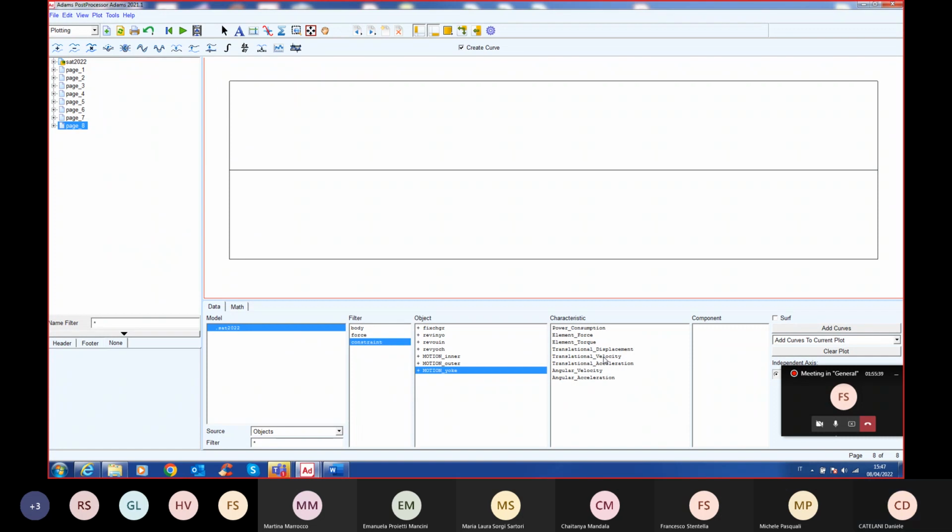For example, we have 3 motions. Every motion is defined with a function of time. And the motion has to actuate a system with inertia. Which is the torque a motor has to apply to give this movement to the satellite? I can select the motion, I can click torque, and I need to know the torque around the z-axis of the joint, component z.